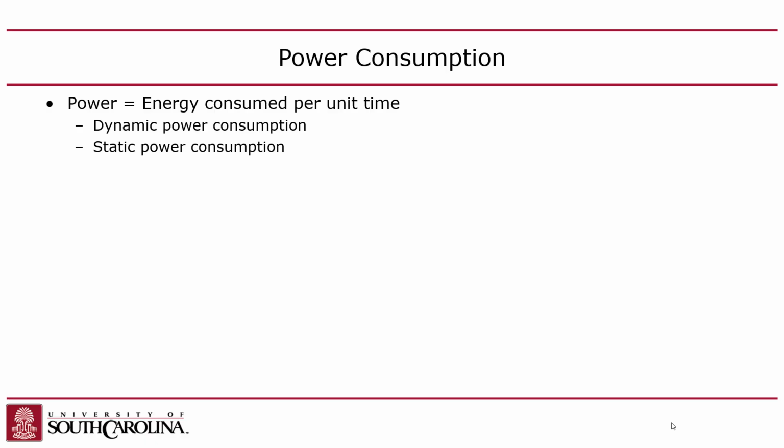When it comes to CMOS, power is everything, right? That's the most important thing. It's even more important than performance because, as I mentioned, current mode logic, which is where you use current instead of voltage to represent a 0 or a 1, is actually faster than voltage mode logic. You can make a multiplier in current mode logic much faster, but current mode logic has higher power. So boom, disqualifies it, right? The old supercomputers of the 60s used to use current mode logic. The original Cray supercomputer used current mode because it's faster, but power efficiency is way more important than performance.